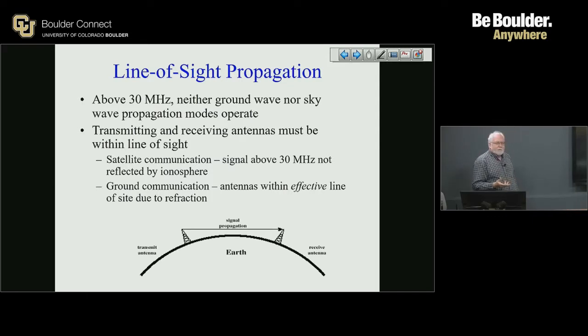We haven't really talked about antenna polarization. I didn't really mention it, but you notice in a Wi-Fi access point, the antenna sticks up. That creates an E field, an electrostatic field, an electromagnetic field. The idea is we want those to end up being created at right angles typically. And that's called vertical polarization when the E field, electrostatic field, is vertical. And that's most of the time what you see in Wi-Fi.